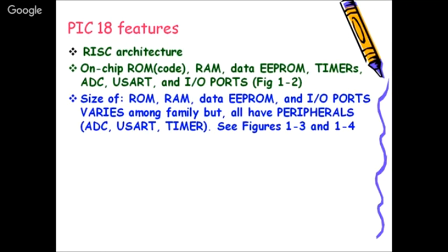Because to access your data, whether data or code, what you need firstly is the address. When you address that thing, then you can access that thing. So particularly in case of the PIC family, the program counter is 21 bits wide. So the on-chip memory can go from as small as some kilobytes to 2 megabytes.